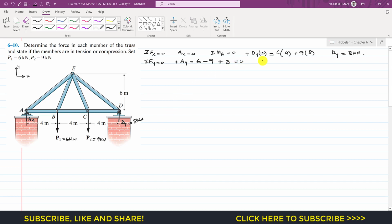So we can find it. AY will be equal to minus 6 minus 9, so this is minus 15, and minus 15 plus 8 is minus 7, so AY is 7 kilonewton. So now we know the support reactions. This AY is also 7 kilonewton. So now I will start with the joint D, since we will solve this by using the method of joints.